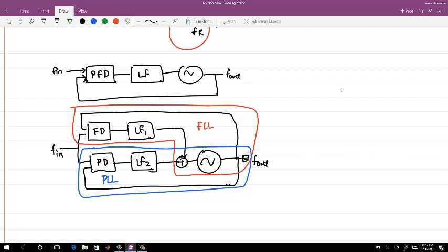We are processing this time information later. So when you do a separate frequency detection, you may not do it in a pulse width modulated manner. Just for an example, if I want to detect a frequency of 1 gigahertz and I have a 1 megahertz reference, I can very well say how much I am counting in the one microsecond of 1 megahertz, and that will still give me a frequency detection. So those kinds of frequency detectors are also used.